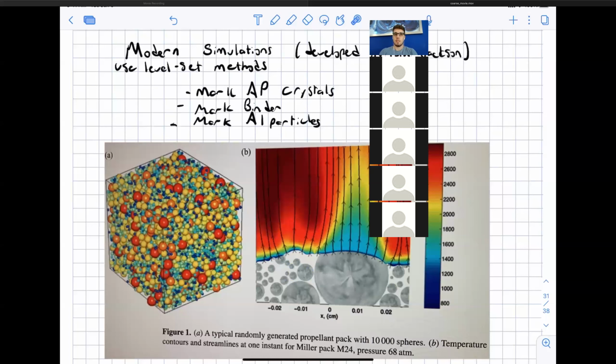And also heterogeneous propellants tend to be used for rockets because you don't really care too much about these particles. But gun propellants tend to use homogeneous propellants because you don't have all these solid particles embedded in the propellant, which for a gun barrel, you do not want: solid aluminum oxide particles flowing at high speed down the barrel.